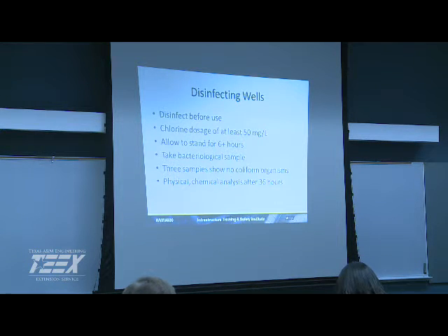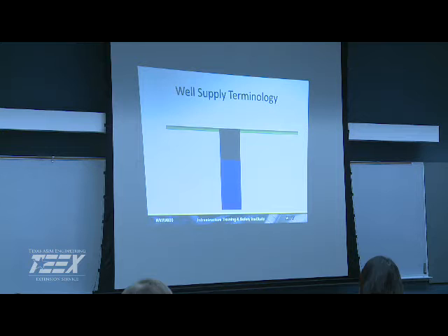And then if you have a new well that's going into service, you're really supposed to over pump it to help develop the well, pump it for 36 hours, and then that's when you want to start pulling your analyses so you can figure out what the water quality issues are. And the good thing with groundwater, once you figure that out, it's normally real stable. I like groundwater a lot. It's real simple in many ways.